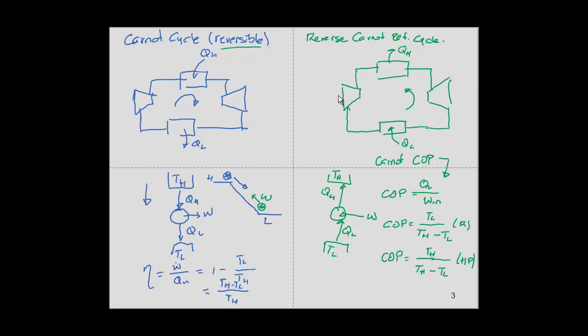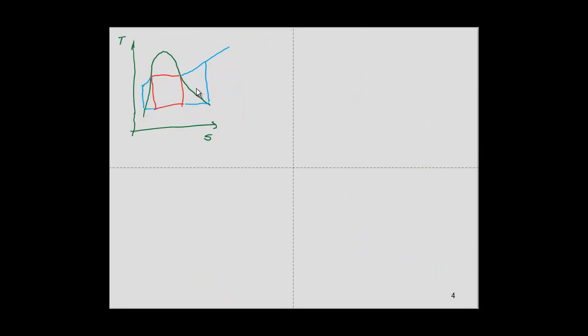One problem we have though is that in this part, this is a turbine. It should deliver some work, and it's difficult for us to build such a small turbine. It's not practical, so what we do is we use an expansion device that will change our cycle. And with an expansion device, when we discuss entropy, we said that expansion is one of the processes that is very irreversible, so the entropy will increase this way.